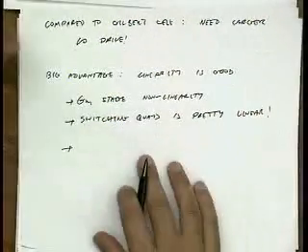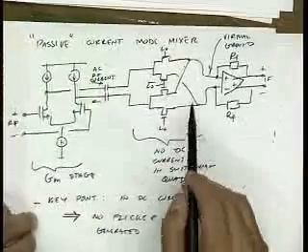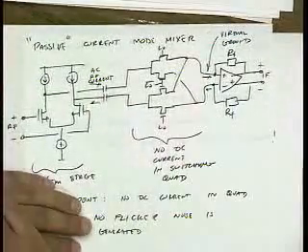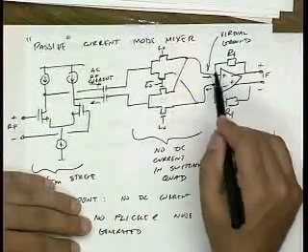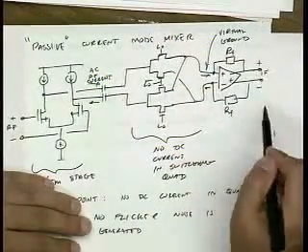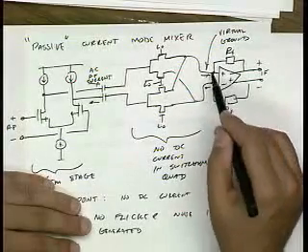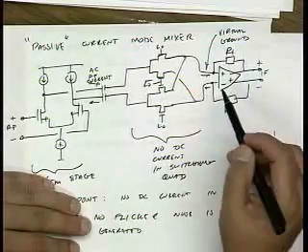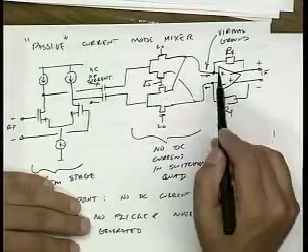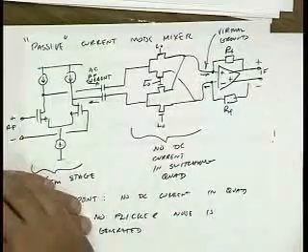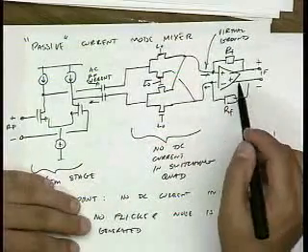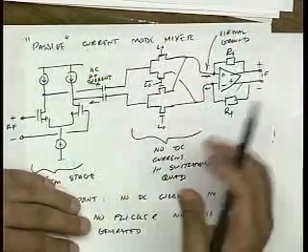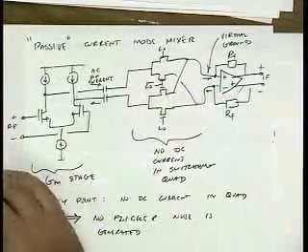And then the output is a current signal. So the current flows into this virtual ground and then flows into this feedback resistor, which produces an output voltage. Because the output voltage swing is very low at this point, because of the low impedance, it's actually extremely linear. And this feedback resistor is just a passive resistor. So overall, this last stage is also very linear. It's an op-amp with feedback. So the overall linearity is very good. It's just dominated by this input stage.